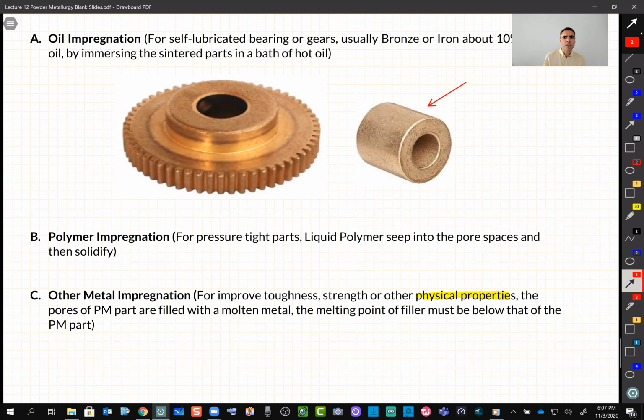So if we want to rank them, on Thursday you will see when we talk about forging. Forging is the best in terms of preventing cracks. Powder metallurgy is second, and casting is the worst. Because in casting, there is a chance that maybe a region of a part doesn't solidify, or a region solidifies faster than the rest, and then there is a higher chance of crack propagation compared with powder. Thank you.